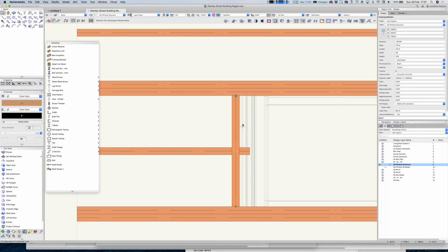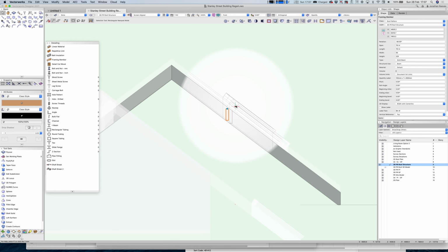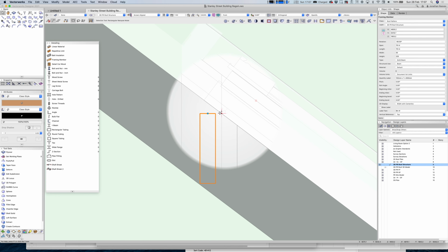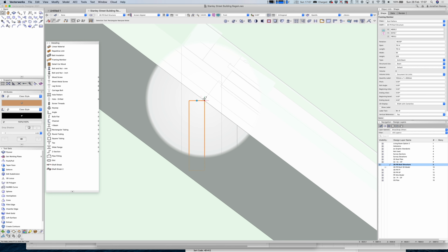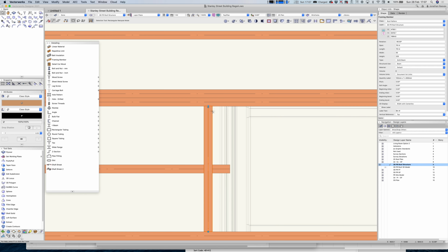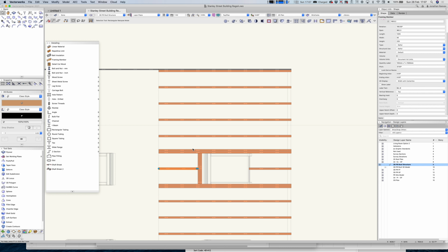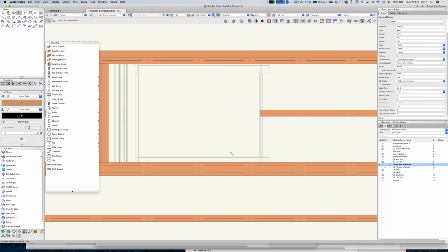Okay, let's drag that across and let's hold down the Alt key. Just checking in 3D where that sits in the section. Using the B key, super useful. I love this in Vectorworks. I love to be able to use the X-ray fill. It gives you very precise snapping, and it means that you can work in 3D without having to revert to wireframe or switch view or kind of turn layers and classes on and off. So we'll do a little bit more adjustment on this. We can take off the 50mm extension on that rafter because that was one that we cut basically. Okay, that's good.